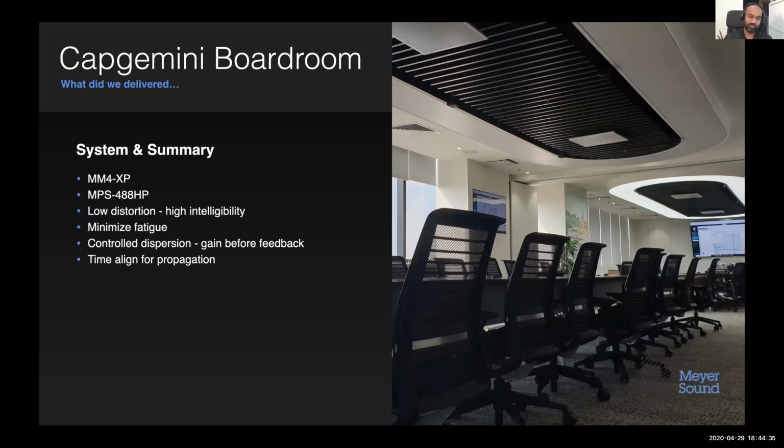It would come out of the speaker at a delayed time, arrive roughly at the same time as the acoustic sound from that person would reach wherever the speaker sound is coming out of. And for this time aligning, gaining control over each loudspeaker output was important. And this, of course, could not have been done if this were a distributed system on a constant voltage line.